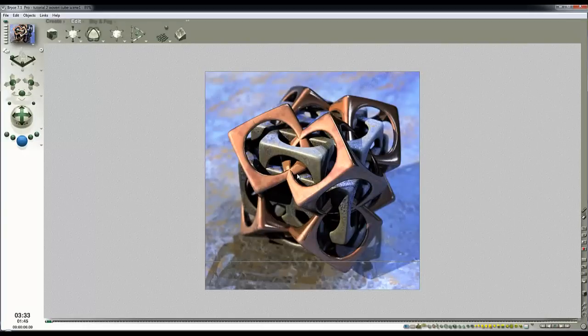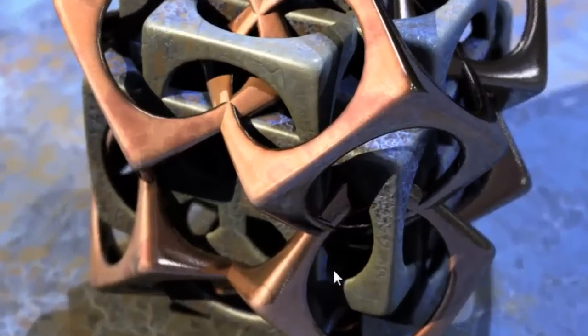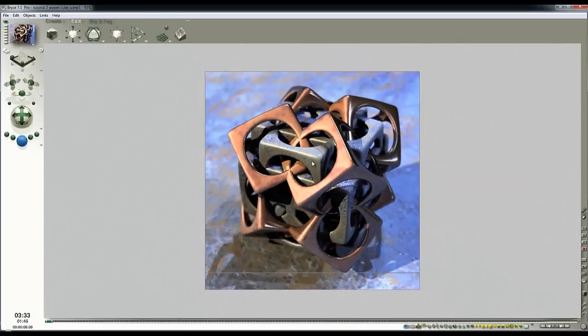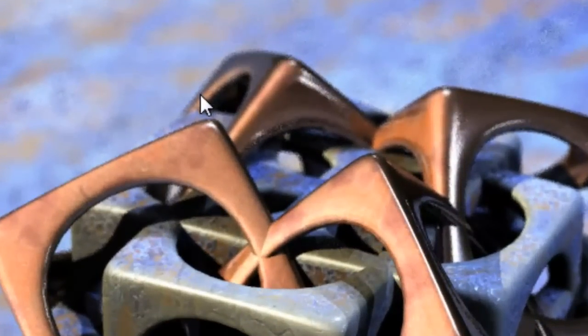I would mention that another advantage of using the premium effects is that the premium effect render engine is an improved version of the regular render, and the extra sampling does add a bit of finer detail to the bump mapping effect on your materials, so you get very nice fine details here. But obviously there is a cost in render time, as you can see, and on slower machines the cost gets higher. Right, and this edge also is looking a bit furry.